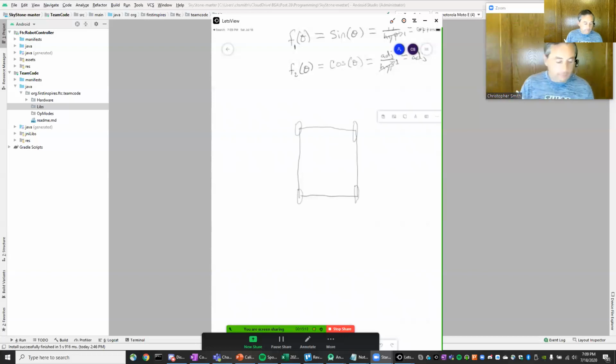And so whenever you have Mecanum wheels, the way I think about setting these up is that if you're looking at the top of the Mecanum wheel, and this is important, top of the Mecanum wheel, you're basically creating what I refer to as the X. The reason why I look at the top of the Mecanum wheel is it's much easier to figure out what's going on when you're looking at the top of the robot, looking straight down. And I want to make sure that these wheels on top are this direction, okay?